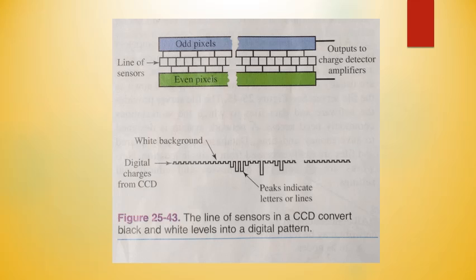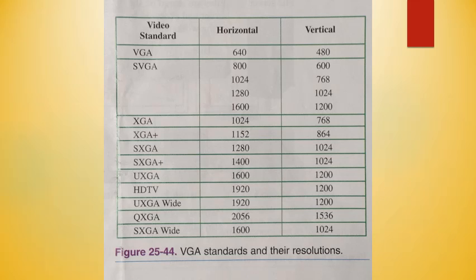The digital camera. A digital camera uses the same technology, or CCD, as the scanner. In the digital camera, the CCD captures all of the lights from the image at once. The individual packets of charge are then converted into a series of digital signals. The digital signals are transferred to a block of computer memory. Once in the computer memory, the data can be manipulated by software.